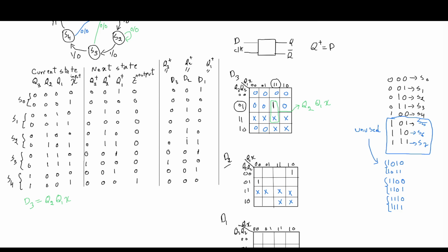We're going to have 1. Next time for D2 where we have 1, it's in this location here. And this corresponds to 0, 1, 0, 1. So that's 0, 1, 0, 1 is in this location. Now the rest are zeros. So now let's do the grouping. We want to do the grouping in the largest group of 1s that we could. So these 2 1s, we can group them with these 2 don't care terms and treat those 2 don't care terms as 1. So this is a group of 4.